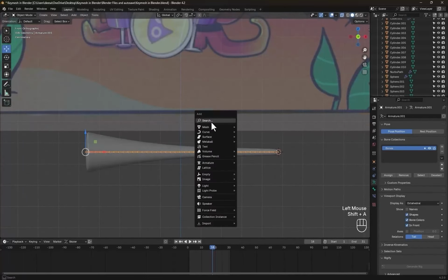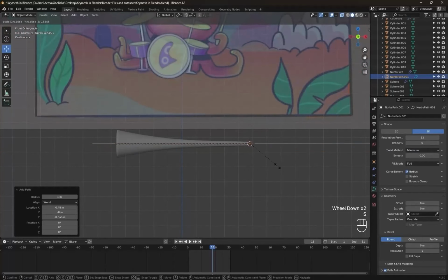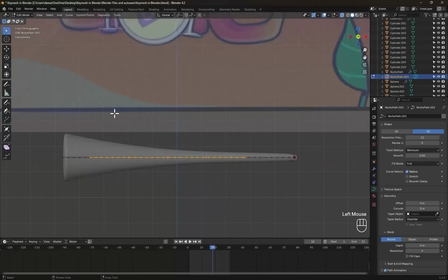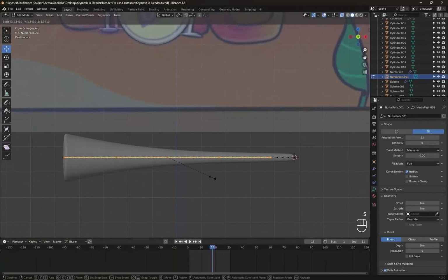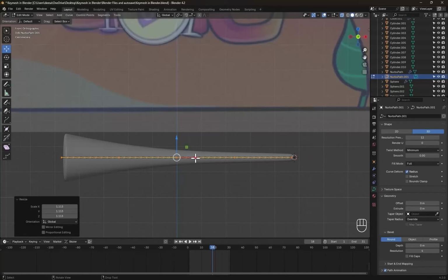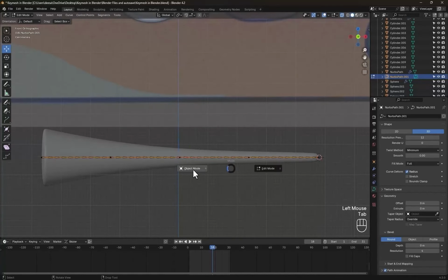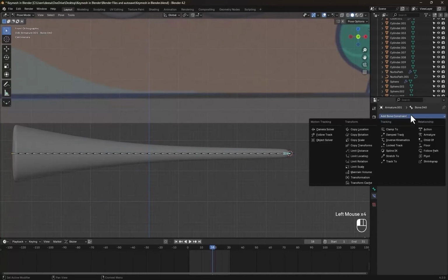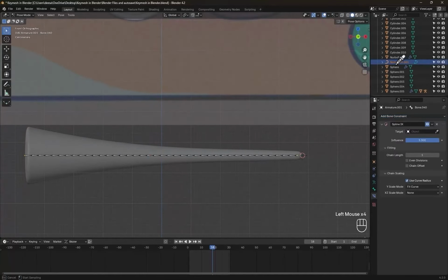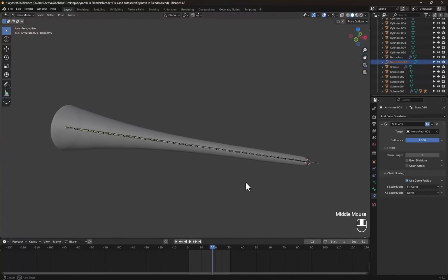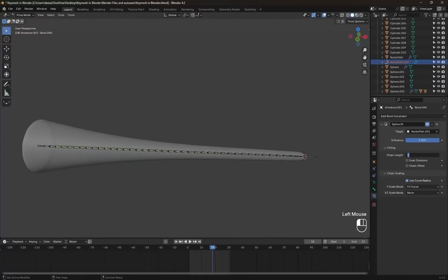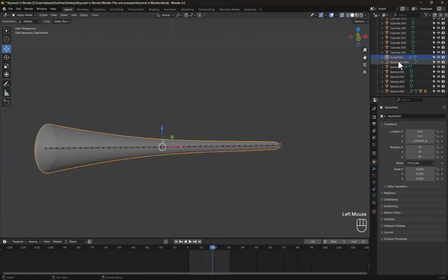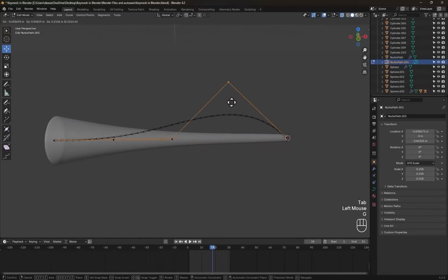Now add another path curve to also match the mesh. Now for the magic. Select the last bone in pose mode and add a spline IK constraint. Choose the curve. Then increase the chain length to be 41. Notice it's same as segments number increased by 1. Now the curve can control the armature.